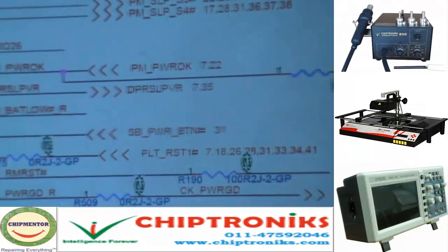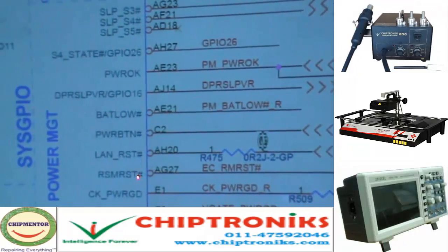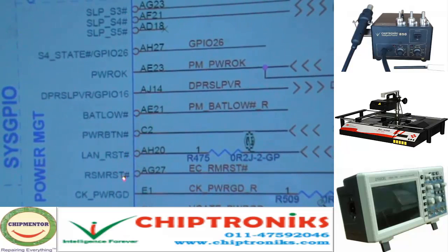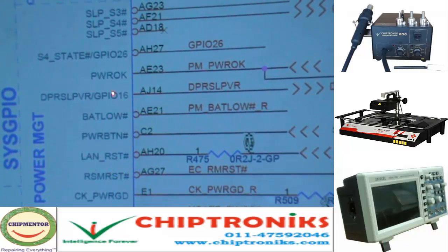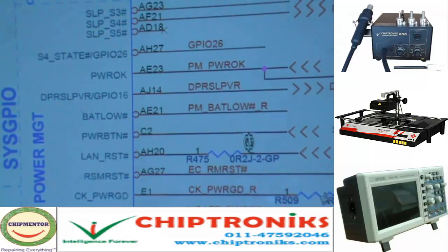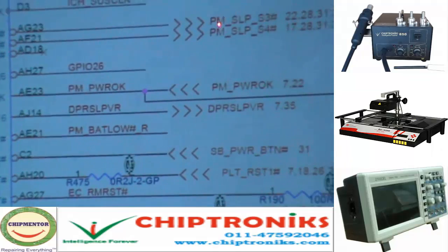RSM reset is the reset signal of this IC. When RSM reset and the power button signals come, it will generate sleep S4 and go into the S4 state.